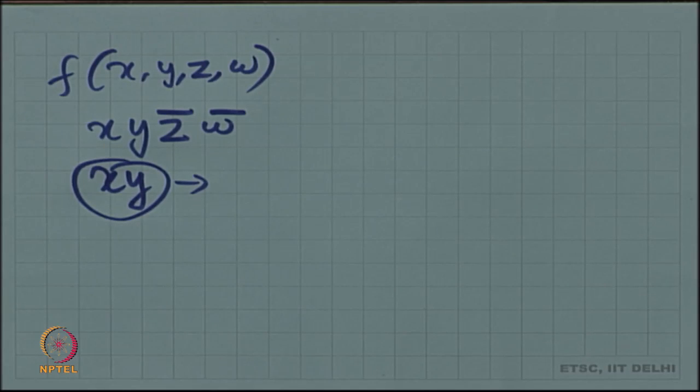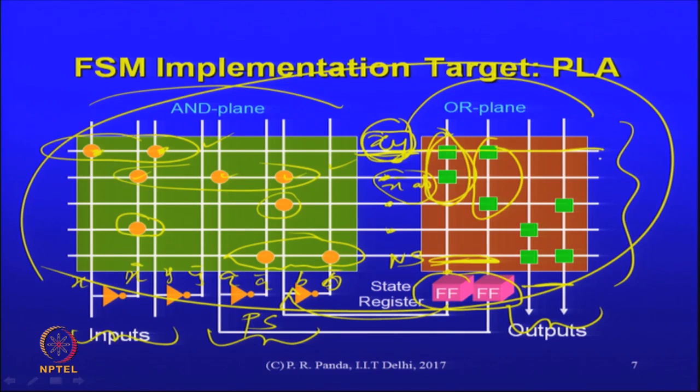What we want to minimize here, if I want to minimize the number of rows, is the number of distinct product terms I am using in composing these expressions. Distinct, because I may actually reuse some product term. It is available for me for use in any of these output lines. So this product term has been used once for that output, also once for this output. I do not count that twice, because that line is available to me, it does not constitute additional area.